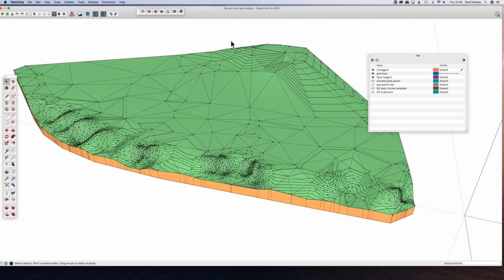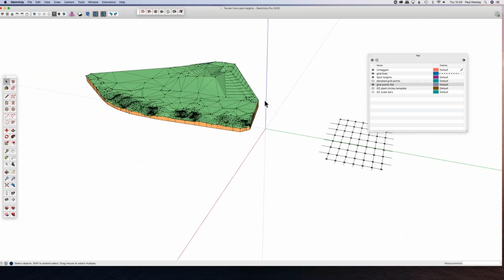If you're creating your own survey and you can't or don't use the perimeter shoebox method, then you're likely to have gone around the garden and measured either using a zip level, or a dumpy level, or some other method of measuring down from a datum. So let me just open up that. I'm going to show you how to create 3D spot heights and the terrain from your own level points.